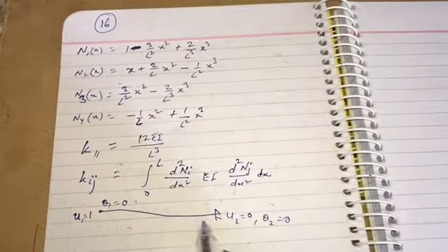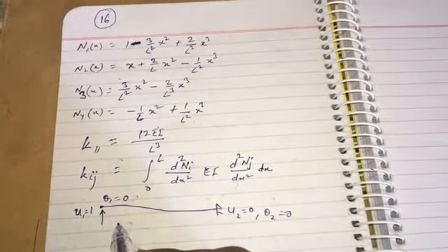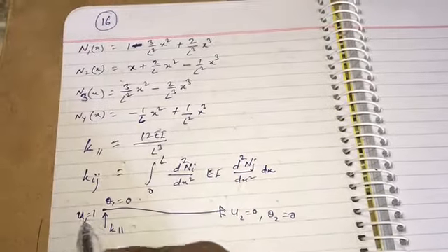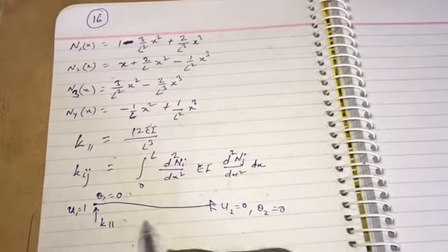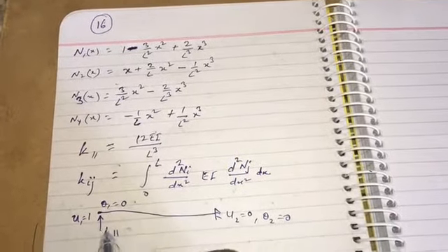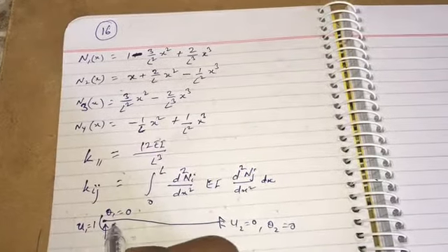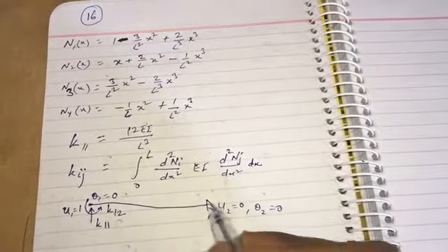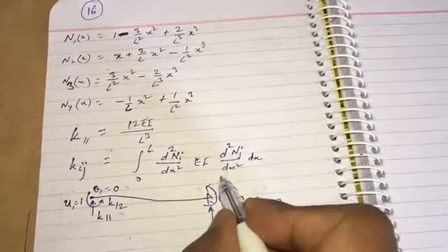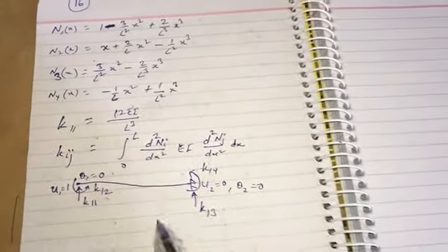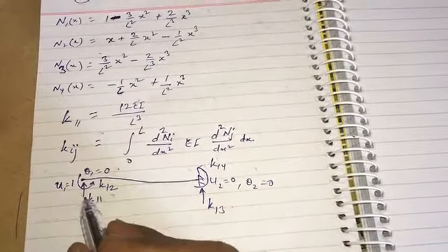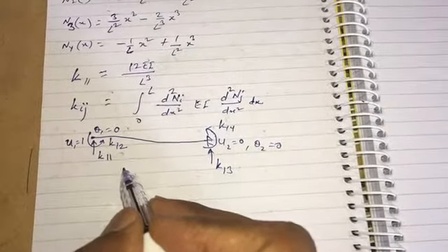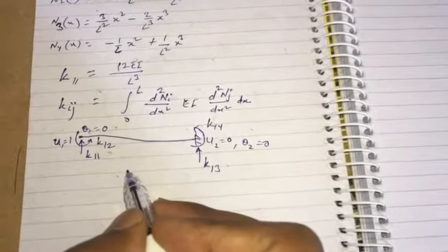In order to get these displacements, whatever force you need will be the stiffness components. The force needed to make u1 equal to 1, theta 1 equal to 0, u2 equal to 0, theta 2 equal to 0 will be K11, and this alone will not do it, so there will be other forces as well. This will be K12, this is going to be K13, and similarly the moment required here will be K14. These are the real forces that have to be applied simultaneously in order to get theta 1 equal to 0, theta 2 equal to 0, and u2 equal to 0. This is the definition of K11.